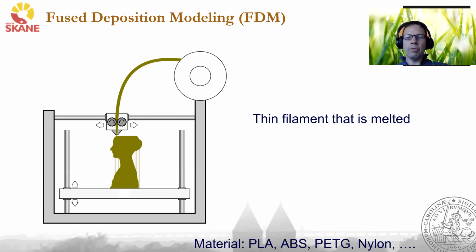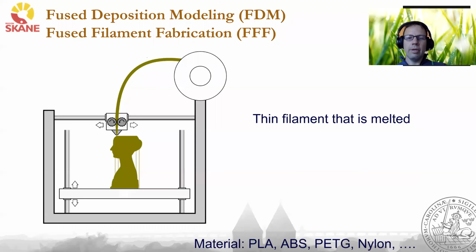I will start with the most common and perhaps the most simple technique that is called fused deposition modeling, or FDM. The company Stratasys registered the trademark for FDM in the late 80s, and they also hold a lot of patents. So the big explosion of home printers occurred when some of the old patents expired. A synonym term that is not trademarked is fused filament fabrication, or FFF. So fused filament fabrication and fused deposition modeling can be used interchangeably. I will use the term FDM throughout the course, just for the sake of simplicity.